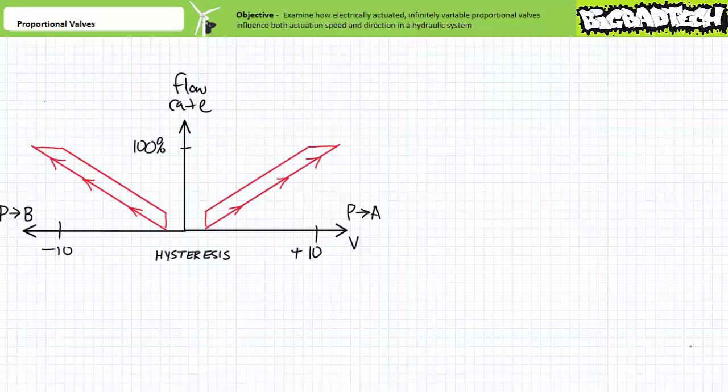Another proportional valve peculiarity is something known as hysteresis, where hysteresis is the spool's tendency to move a predictable amount for increasing voltage magnitude, however, exhibit different amounts of movement for decreasing voltage magnitude. I like to think of hysteresis as the magnetic equivalent to friction observable as slight spool misalignment for equal applied voltages. An analogy might be placing your foot exactly in the center of a tread going up the stairs, but slightly off-center of the tread when you go down the stairs. You're still going up or down the stairs, but you're ever so slightly off position pending direction of movement.